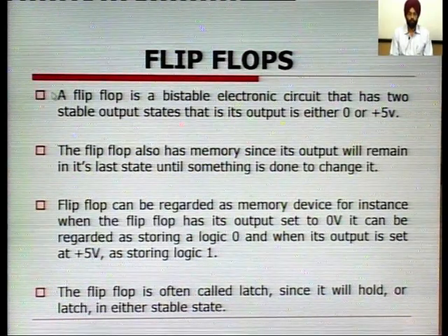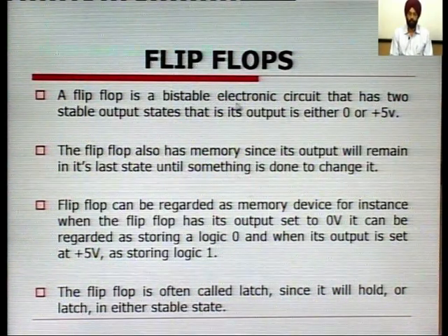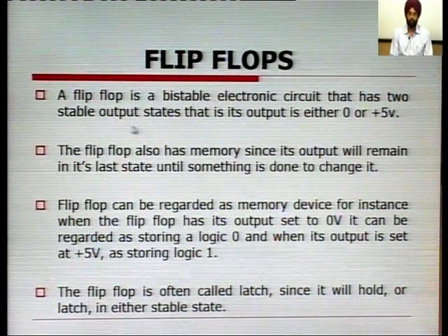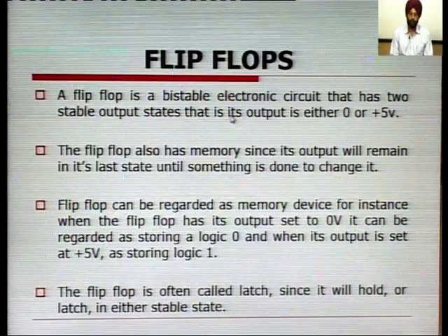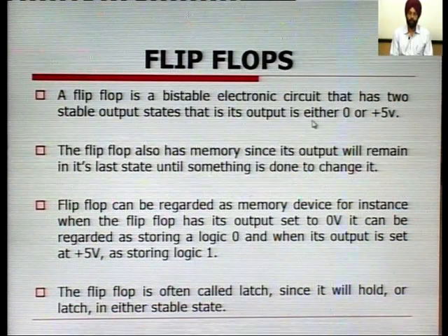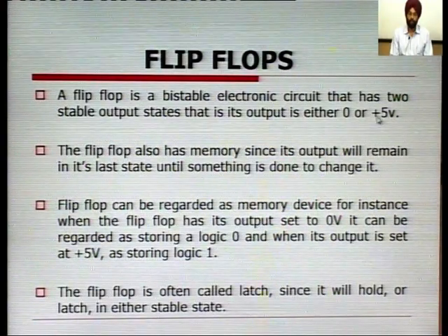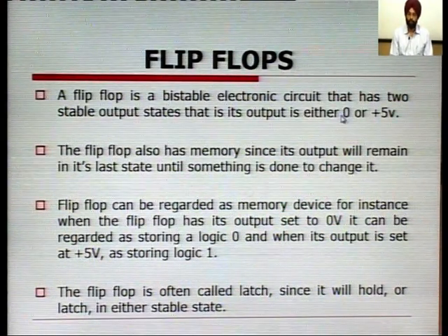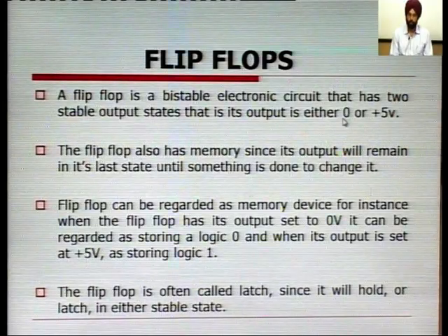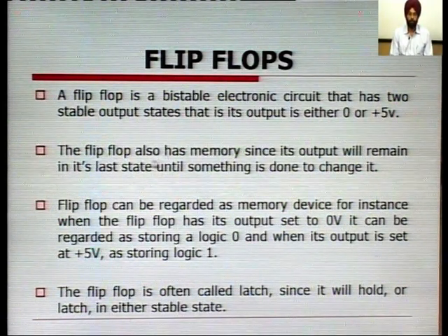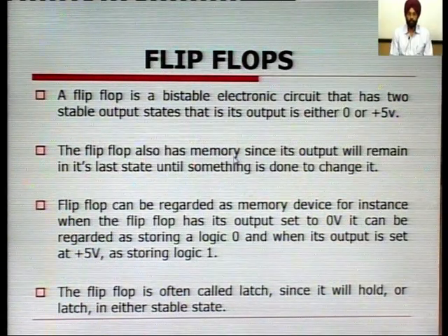A flip-flop is a bistable electronic circuit that has two stable output states, that is, its output is either 0 or plus 5 volts, or we can say its output can be either 1 or 0, or low or high. The flip-flop also has memory. What do we mean by this?